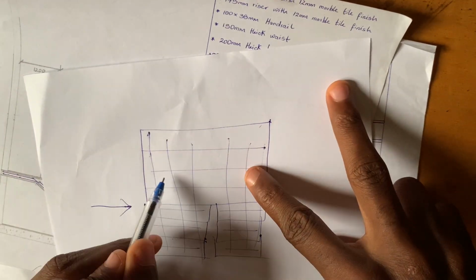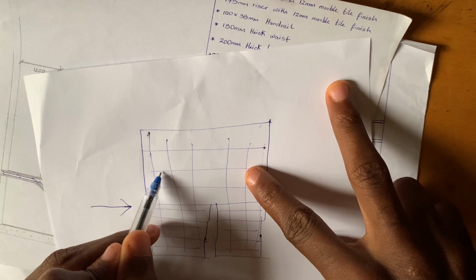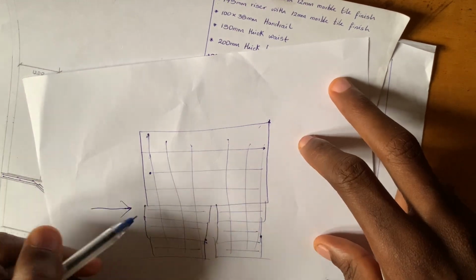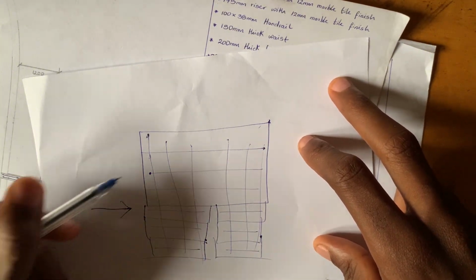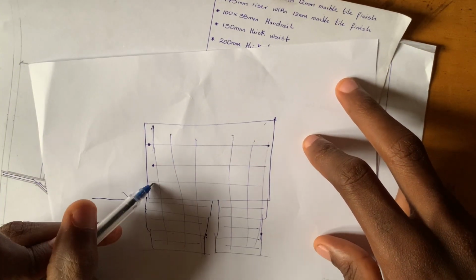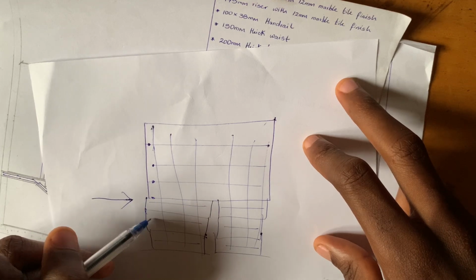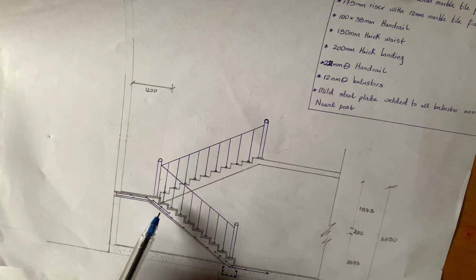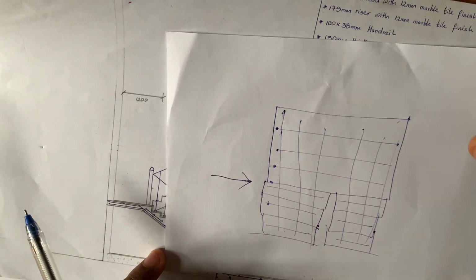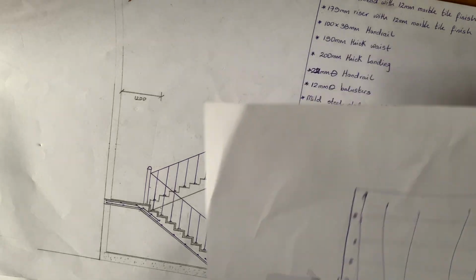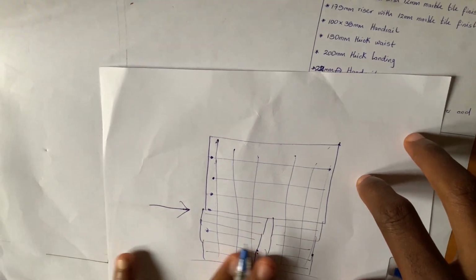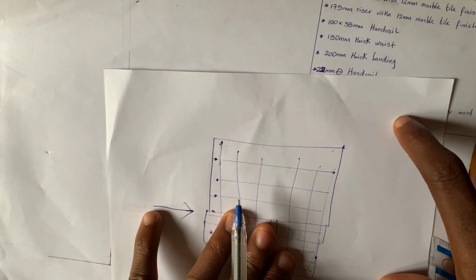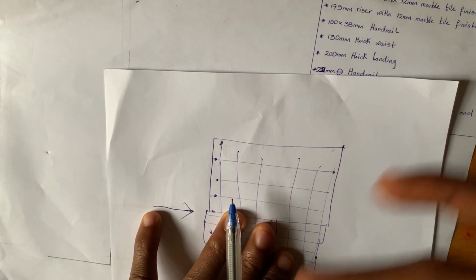So you know that these distribution bars are like cylinders. So from this section or from this view, you're going to be seeing them as what? Dots. And that is why we have them like this. I hope you're getting the logic. So that's for the main bars and your what? Distribution bars. Now I'm trying to expatiate, because this knowledge alone can help you at least measure roughly the reinforcements.